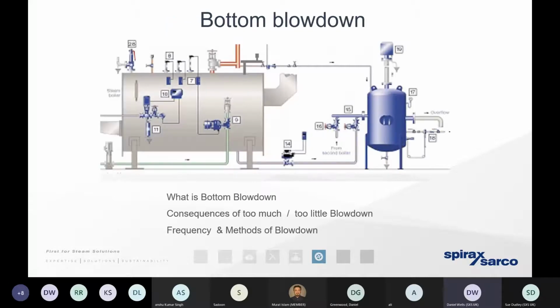And then we know that we've got to maintain the water chemistry of the boiler. If we're putting all those chemicals into the feed water, that together with the chemicals and minerals that are present in the raw water, it means that over time, as the water's evaporating to produce steam, we're going to find that a lot of the particles, a lot of the minerals will solidify and fall to the bottom of the boiler as a sediment. And over time, that can back up past the heat pipes and create a critical failure.